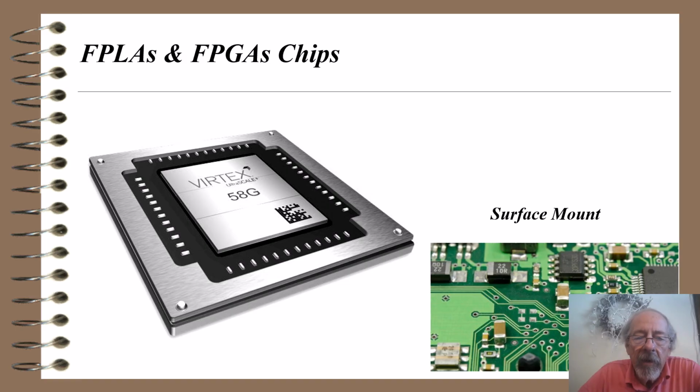So here's a Zertec. I'm not sure if it's an FPLA or an FPGA. And again, surface mount shown in the bottom right little picture there, where these things are mounted on the surface of a printed circuit board. And the pitch of those things, you see the big chip on the little picture there. There might be a space of one or a couple thousandths of an inch between the pins. Very difficult to remove a part like that off of a surface mount board.